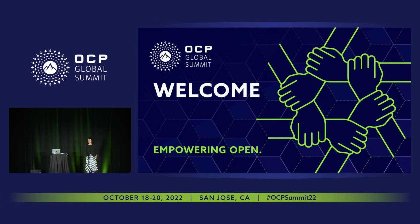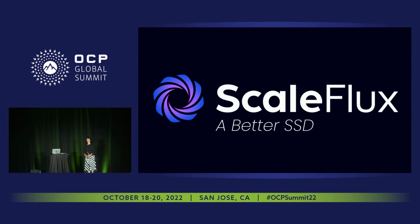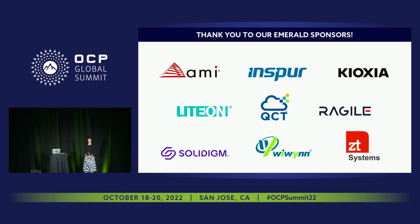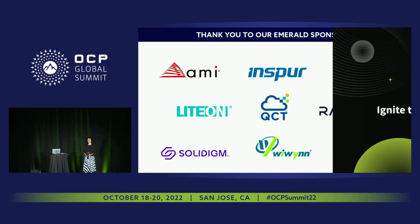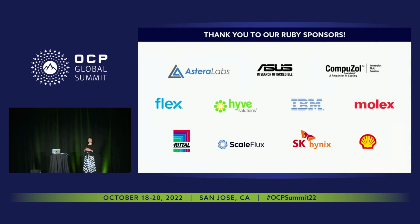One question I have is, why would you offer a chip-first process when the chip-last process has several advantages? That's a very good question. Why do we want to offer it? The chip-first can provide a little bit higher performance, because for chip first, I don't have the micro bump in between. So my die can make a short link to the RDL. But for chip last, I have to use a micro bump between the die and RDL. So this is one reason.